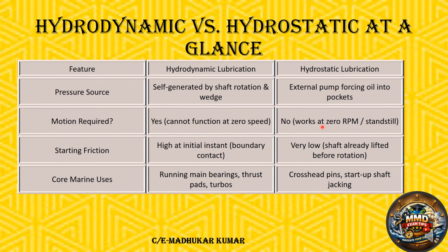But it is not like that in hydrostatic. Hydrostatic lubrication does not require any motion. An external pump will pressurize the oil and separate the journal, and in a standstill condition also the hydrostatic lubrication happens. Starting friction: high at the initial instant in hydrodynamic, boundary contact, some of the spaces have contacts. Very low in the starting for hydrostatic. Why?